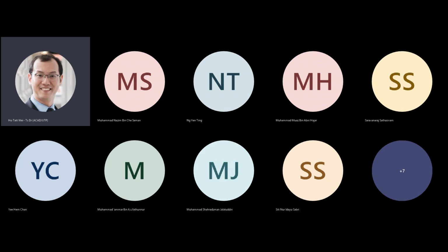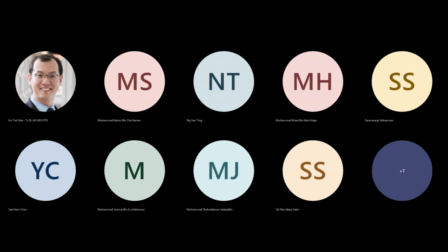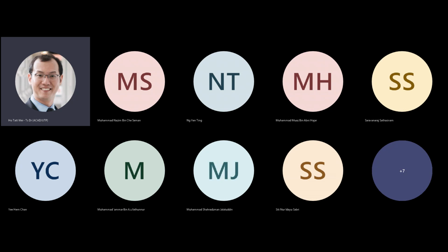And so now you start to realize that you are not limited to the 2 input AND and OR gates that may be in your digital electronics course as an undergraduate. You can design a whole plethora of different gate configurations, right? So starting with the NAND and the NOR and the NOT gate. And you can have multiple inputs, outputs. And the text and some of the reference material also shows you other kinds of interesting gates, such as the AOI, OAI. You can have buffers. So this is AND-OR-invert. This is OR-AND-invert. So it's actually implementing the product of sums and the sum of products from your digital logic implementation.